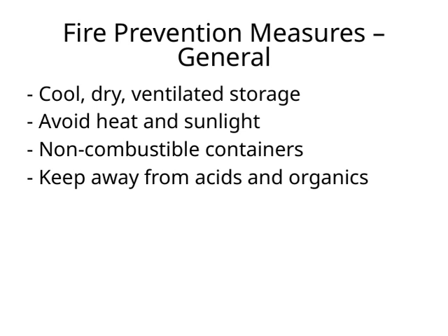When choosing containers, opt for non-combustible materials to reduce fire hazards. Additionally, make sure to keep combustible materials away from acids and organic substances, which can be reactive and increase the risk of fires or explosions. Overall, these precautions are crucial to maintaining a safe environment and preventing fire incidents. Remember, proper storage is a key part of your overall fire safety strategy.